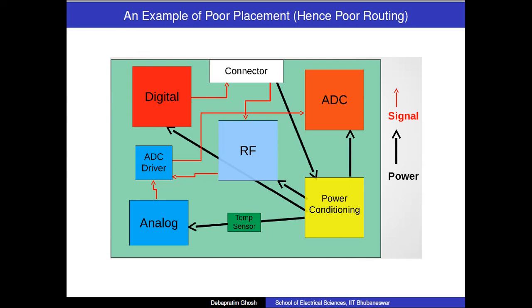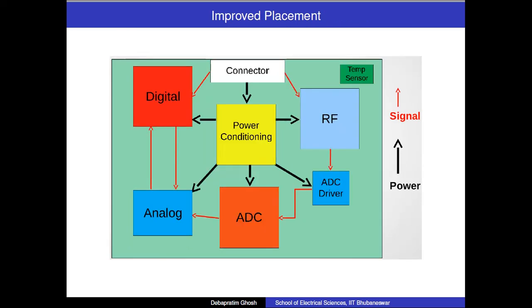A better way to do this placement is this way, where you are placing the power block in the center. Now you can see that the connections are much shorter and there is hardly any overlap, and therefore the noise can also be reduced in this way.